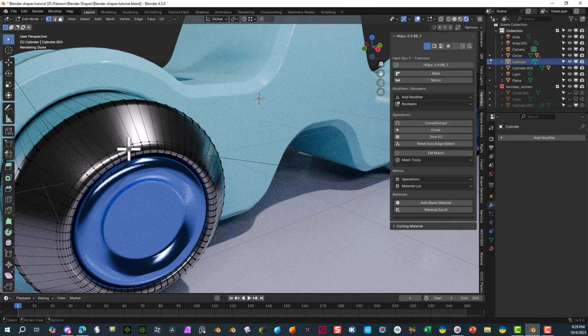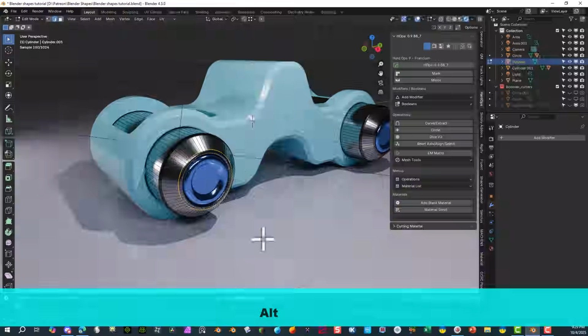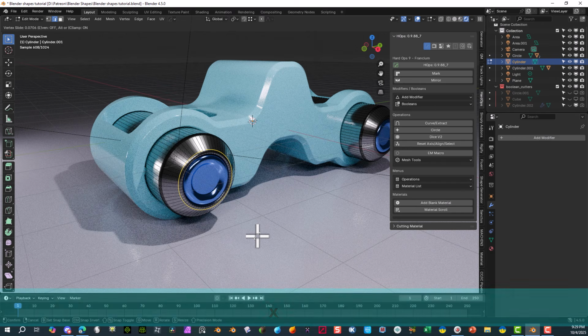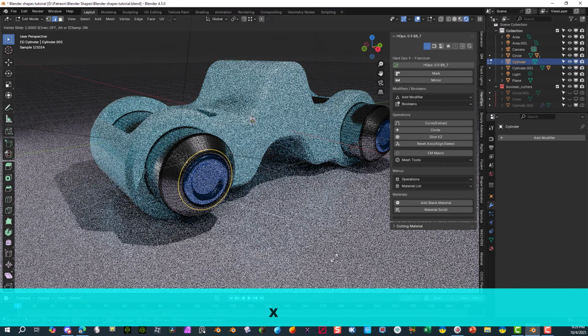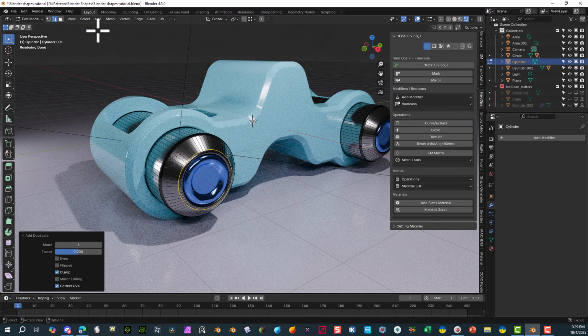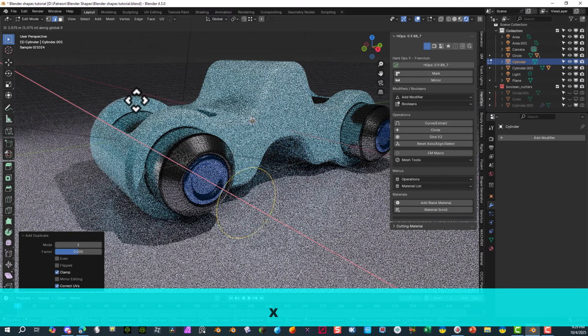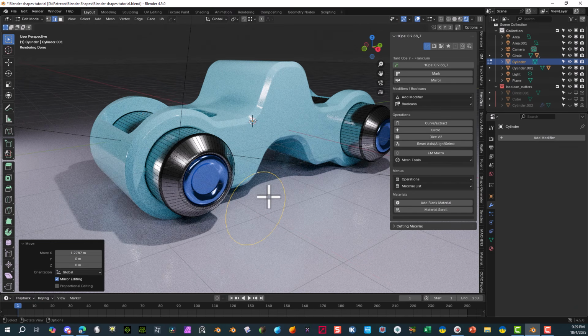So we're going to select this line here with the Shift, with the Alt key. So select this line right about here. We're going to use this to help us drive a nice cylinder. So select, Shift D. We're going to hit the G key, and then on the X, we're going to move this out. It doesn't go right away. Hit it again, G, X, and move it into place, away from the other objects so we can see what we're doing.